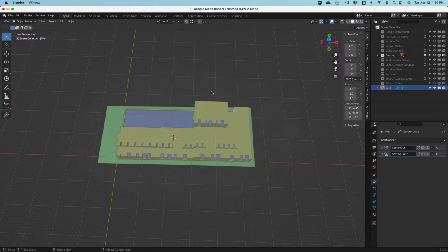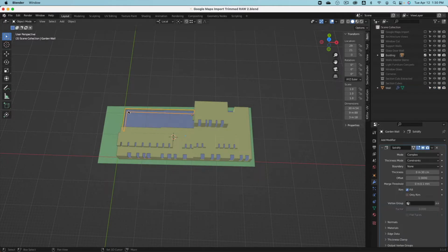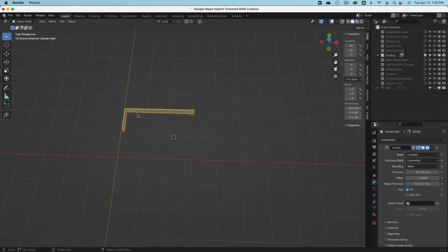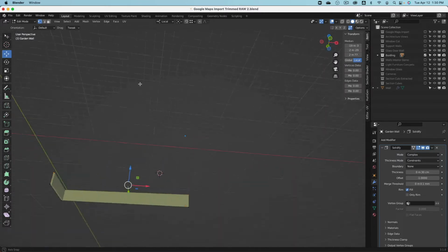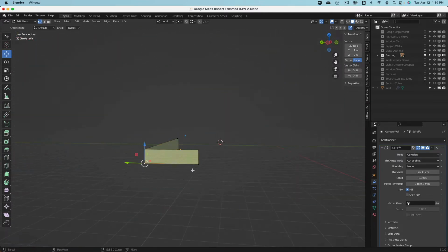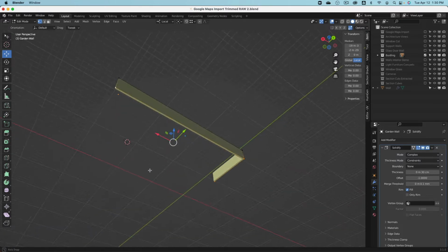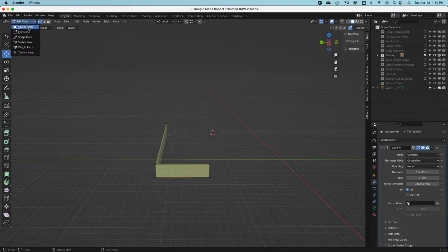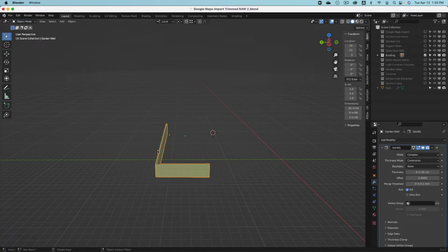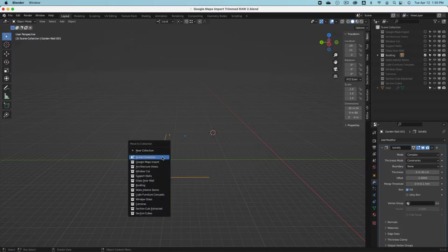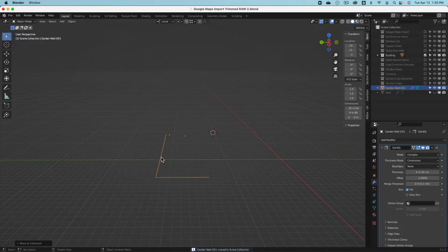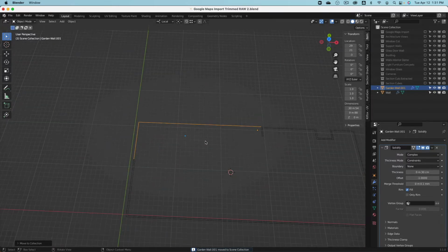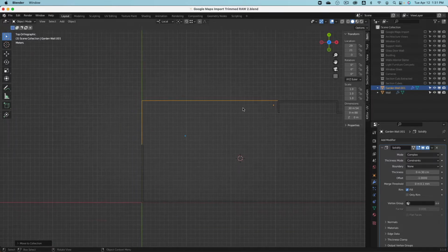I will show the building here one more time. Go to this object, Shift H, hide everything else, go into edit mode. Here I will select these points, Shift D and escape, P and separate. That's the key shortcut. H, hide this, and then this with M, I move into scene collection. Very good. Like this, show this. 7 for the top view.